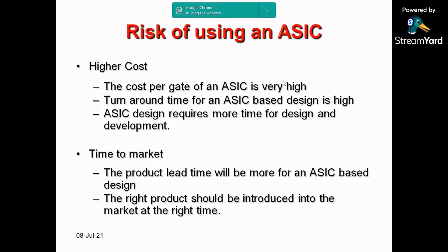Risk. Suppose I want to build my own IC for a specific application. The only risk I can say is time and cost. Time, of course: when you start the design, you need to decide whether to go for a standard cell design or for semi-custom. I'll be telling you about the semi-custom. So it is the time taken from the design till the fabrication, the GDS file. The GDS file is the file that you need to give to the fabrication for fabricating the IC.